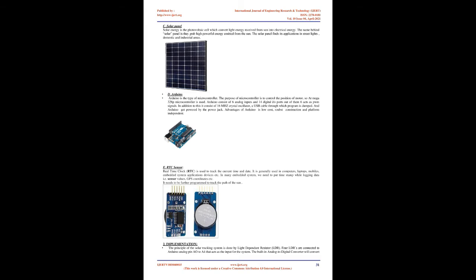9. The paper 9 shows the study has compared the voltage, electric current, power, and efficiency of a solar tracking system using 2- and 4-sided flat mirror reflectors with angles of 90, 120, and 150, between the solar panel and solar flat mirror reflectors. The electrical current, power, and efficiency of the 4-sided flat mirror reflector system were better than those of the 2-sided flat mirror system only when there was a suitable angle, 120, between the reflector flat mirrors and the solar panel due to the higher solar ray input.